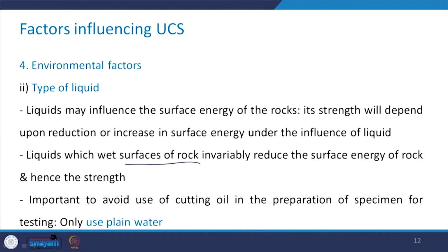Liquids may influence the surface energy of the rock, and the rock's strength will depend upon whether the surface energy is reduced or increased under the influence of the liquid. It has been seen that liquids which wet the surfaces of the rock invariably reduce its surface energy. And as I explained, the moment the surface energy of the rock is reduced, its strength is going to be reduced.